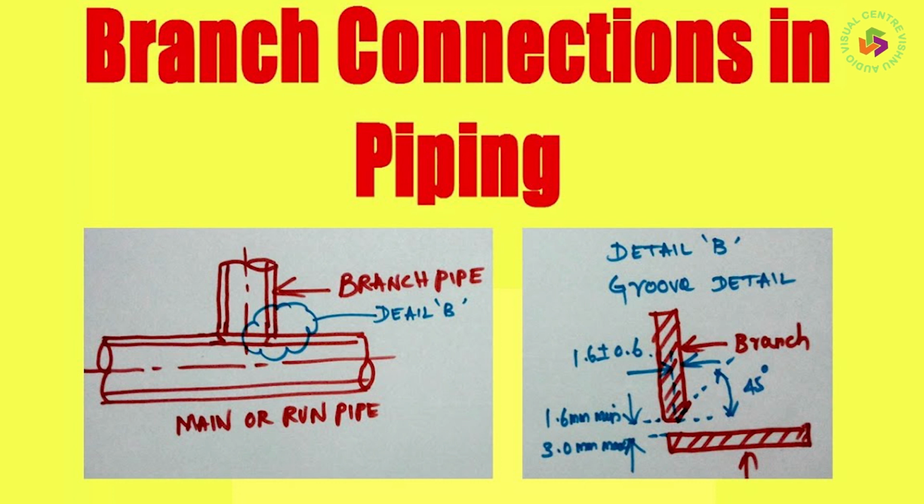In that connection, we mentioned that we start by assuming a discharge value, and then based on that discharge, in each loop, we calculate the head loss for each pipe in that loop, and finally the net head loss in each loop.